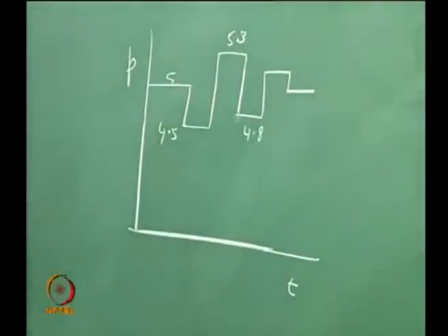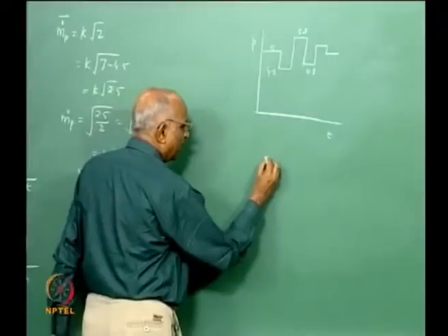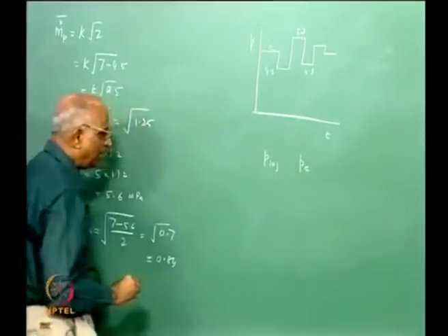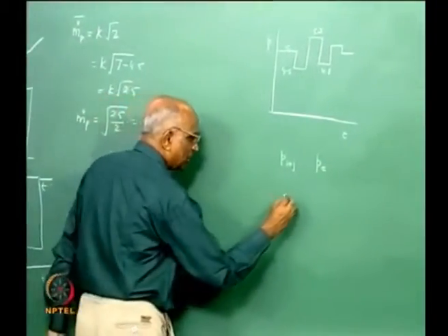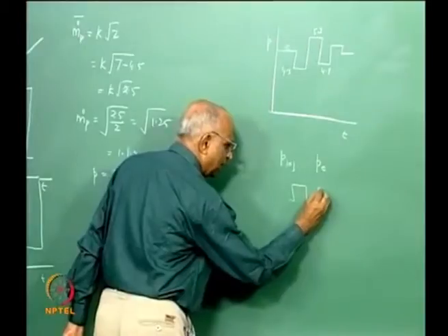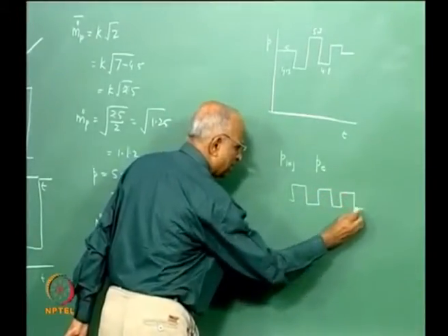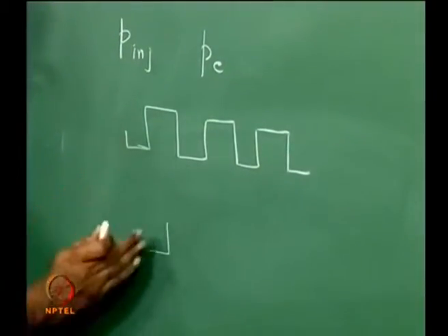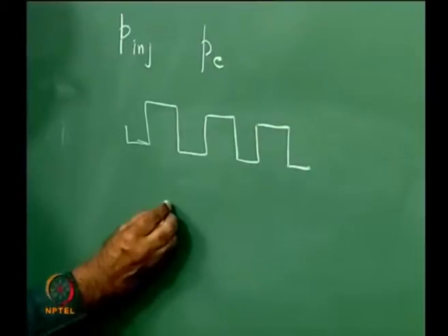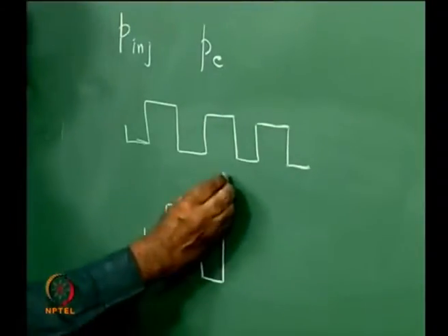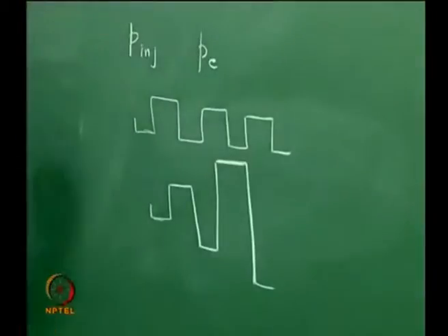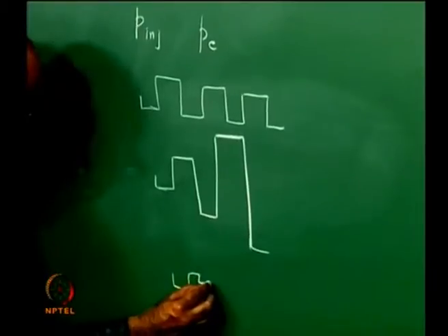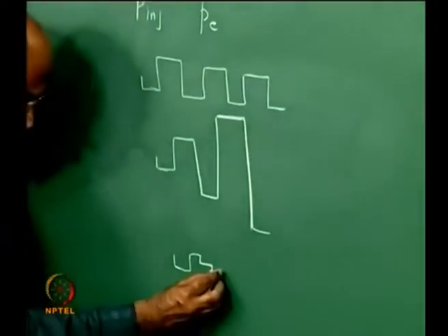Therefore, what we have just done is we have taken a simple case wherein we varied the injection pressure, kept the chamber pressure constant, and we found the oscillations either keep on oscillating in a limit cycle mode, with the same amplitude, or it could diverge out like this and ultimately explode, or I could start like this and it keeps decreasing with time and reaches this.